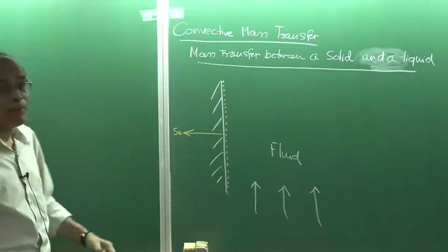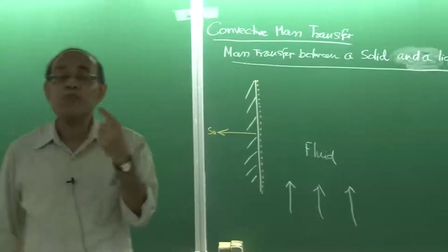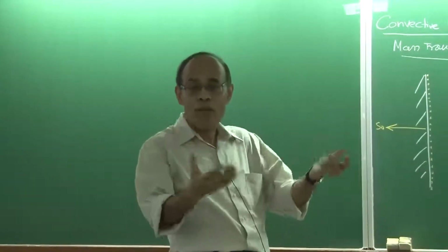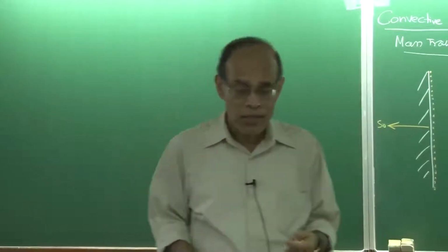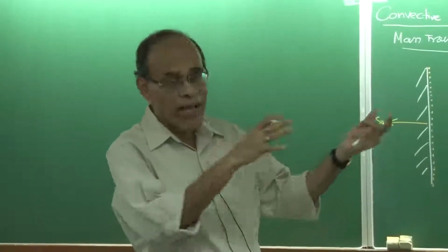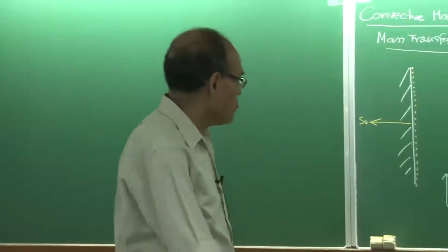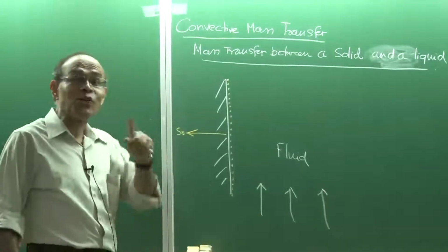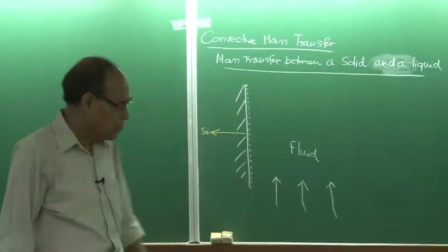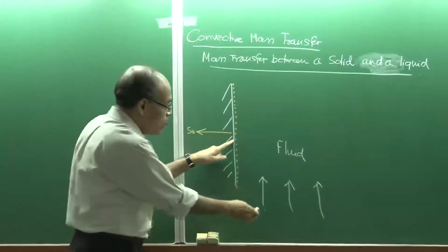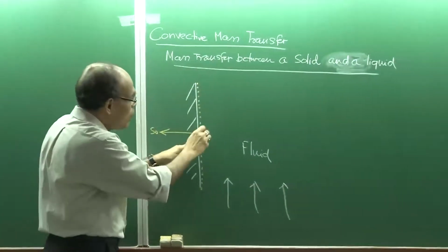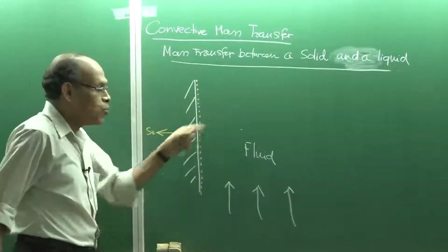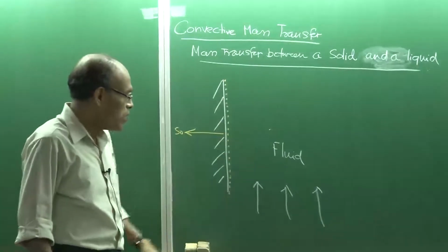We'll discuss the applications, but I can show an example with respect to leaching. Okay, leaching, as you all know, you take bauxite, you take sodium hydroxide, you have studied that, and you get a leach solution in which all the alumina from the bauxite gets into the leached liquor, and it becomes sodium aluminate. So that is a solid-liquid mass transfer in the Bayer process, for example. And so the solid is there, the fluid is flowing past the solid, and as a result the species which is present in the solid progressively dissolves into the liquid.